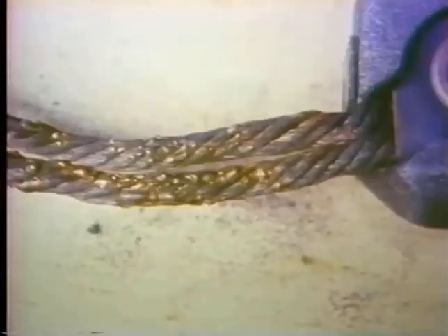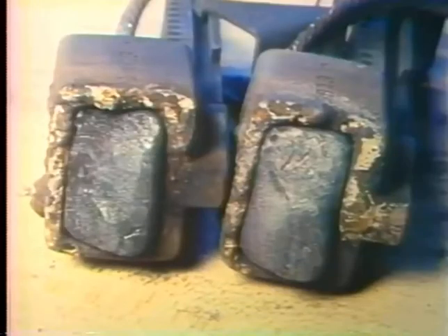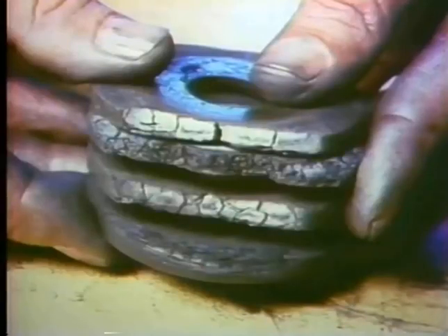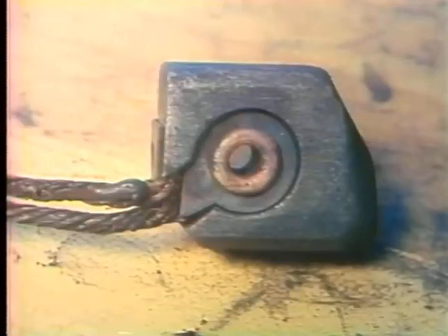The results of flashover can be very severe. Melted brush pigtails, burned brush holders, charred brush rigging insulation, and burned brushes can all happen in a flash. In addition, the commutator is likely to be severely damaged. You may have to replace and seat all the brushes and replace or at least clean and dress up all the brush holders. The brush rigging may have to be replaced or at least cleaned.